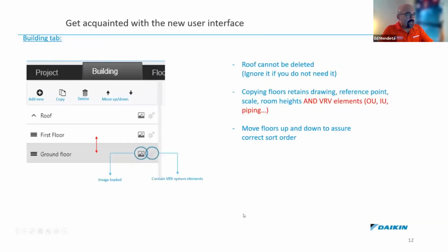In the first area that I showed you, which is the floors, you can move those floors or change the location of the floor. Of course, when you change the floor, you also have to change the labeling of the floor. You can do that either by moving this gray area physically up and down with your cursor, or you can click on this move up down button.